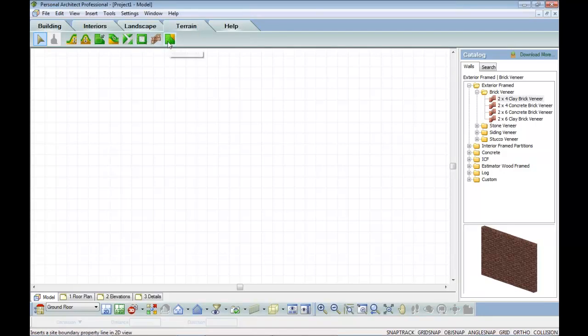The Terrain tab gives you a full 3D terrain editor, so for things like hills and valleys. You have a full site design tool for lot design. You have retaining walls and paths and pads. And then at the side of the screen, this catalog, which is fully compatible with products like TurboFloorPLAN or Envisioneer, is really where all your objects are kept.